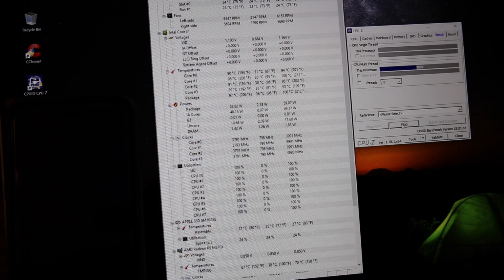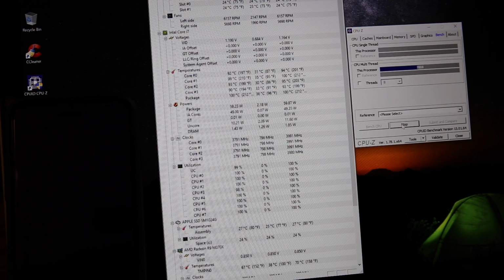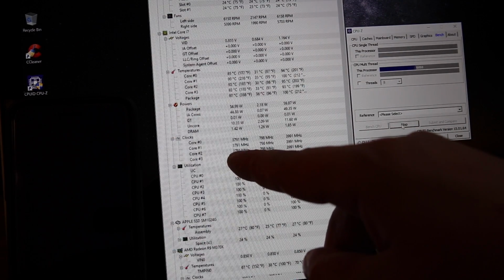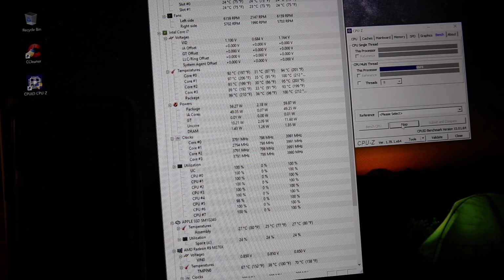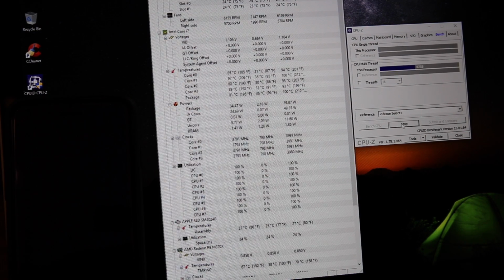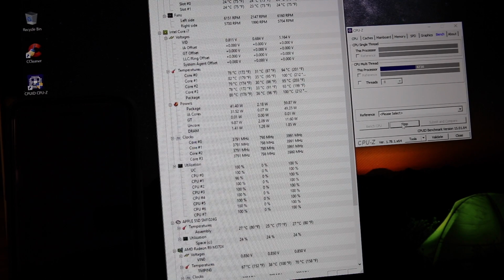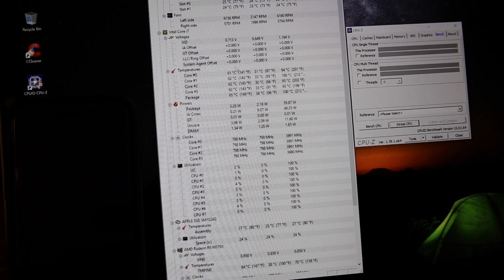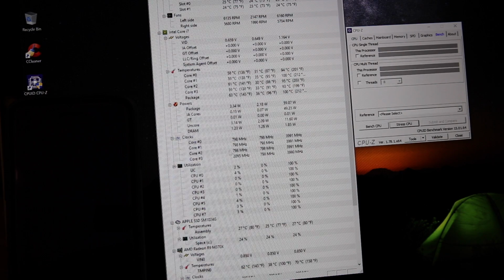So exactly that happened on any laptop, not only on the Mac. When the processor is too hot, he will lower the frequency, he will lower the clock. So it's like I bought a 4 gigahertz turbo mode laptop, and I use it at 2.7. It's depressing. So what can we do about that? Let's check. If I stop stressing the CPU, you'll see the temperature goes down quickly. The clock goes down to idle mode.